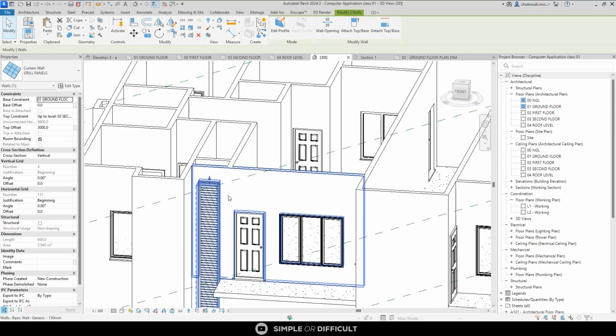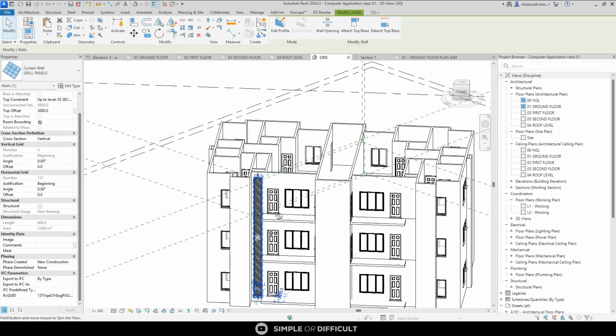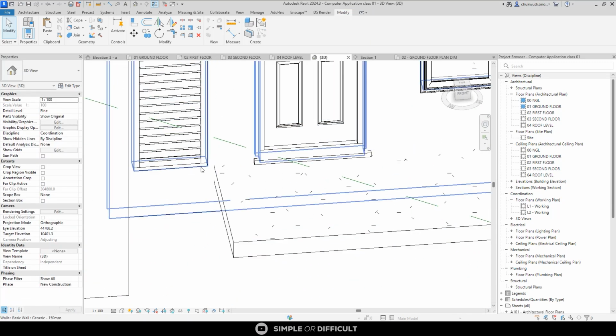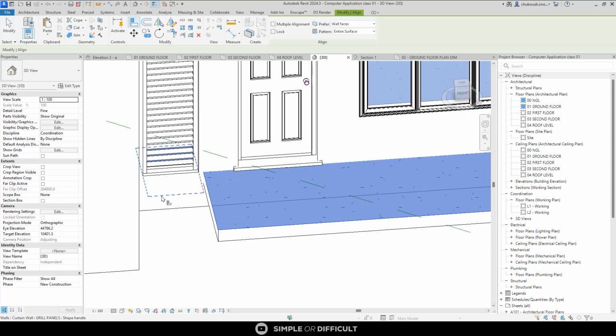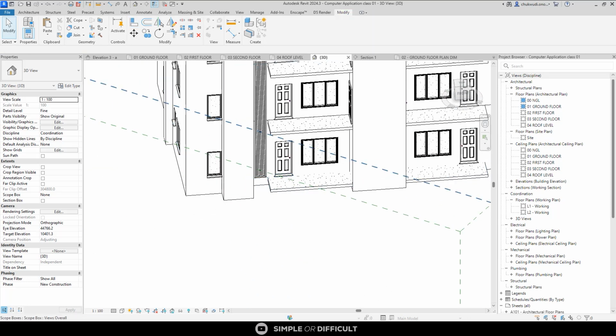The width of this is 600, whereas the height, the unconnected height is 9,900. In case yours isn't like that, you should now be able to set it properly and make sure that this flushes properly where they're supposed to flush. Okay. You can see it flushes on that floor. Okay, so make yours flush there.